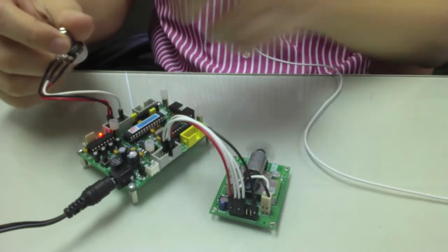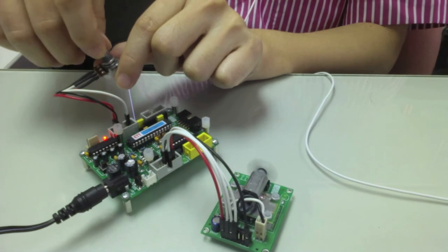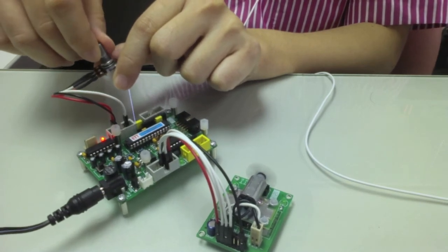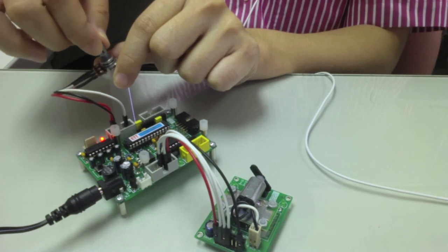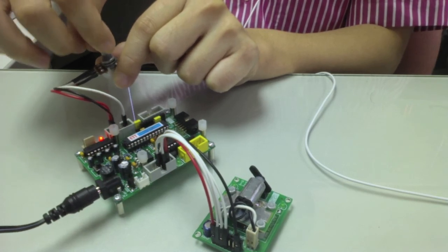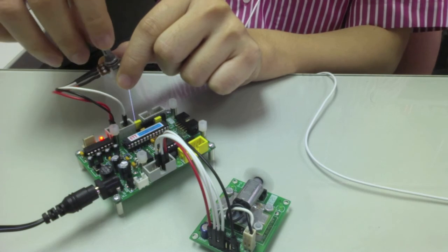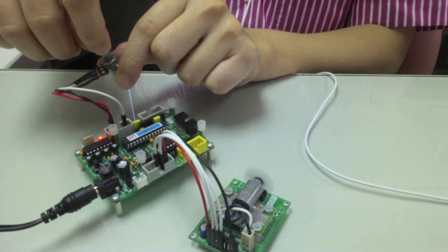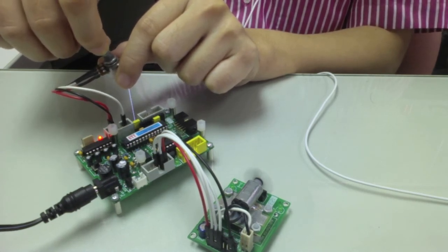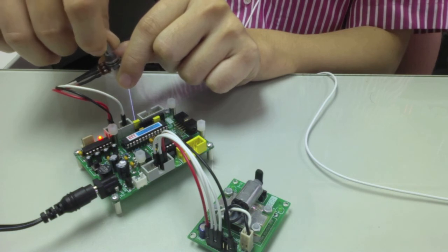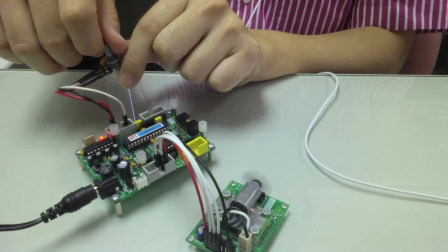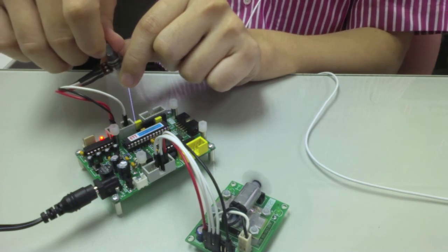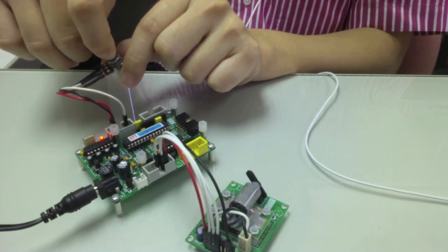But if you got it right, this is what happens. I make a few turns of the potentiometer. Here, it's gonna stop. And then when I turn it to the other side, it's gonna turn in another direction like this. So basically, I use the potentiometer to control the speed of the DC motor by generating different pulses. You might want to open the console to see the value reading from the potentiometer.